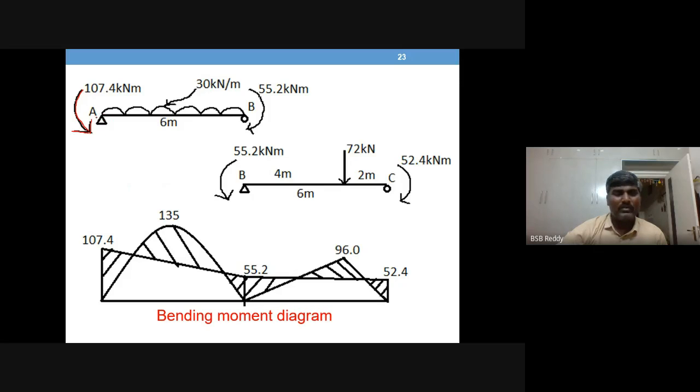Now you see I have drawn a partial free body diagram where I have not completely removed the fixed support. I have removed only the moment reaction from the fixity. Then I have kept vertical and horizontal support reactions in terms of a hinge support. So I have kept a hinge there, with two reactions.